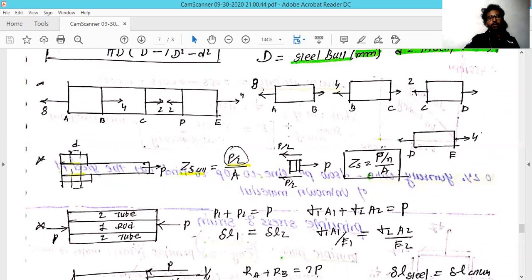First, draw a vertical line between the A and B cross section. Now you have to move to the right side of the diagram. When going to the subsequent cross sections, you have to decide on a single direction. In this direction, I'm going to select the forces only on the left side.